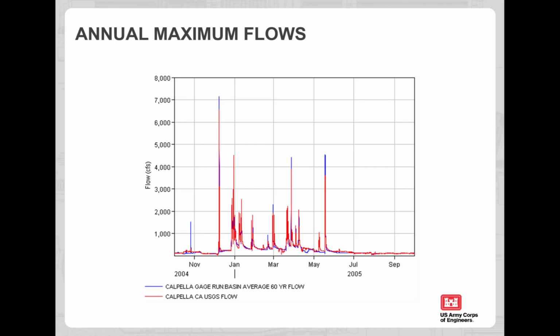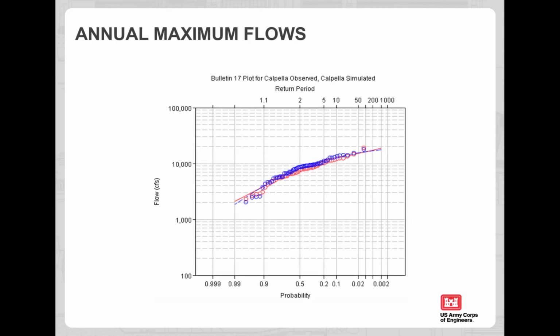If we were going to do a single water year calibration, we would focus on individual hydrograph peaks. Peak flows are sensitive to the infiltration rate in the soil loss model. For the period of record, we adjusted these parameters while graphically inspecting the flow frequency curve. The focus of calibration was overall correlation between computed and observed flow frequency curves with emphasis on low probability events, since the study was focused on flood risk.